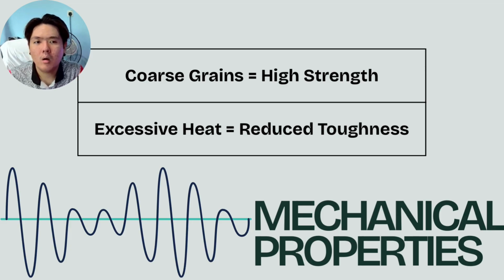So why and how did we determine this problem? I would say it's a problem in welding. Maybe you're using too high a current, maybe you're too slow on your travel speed, or maybe you're doing many passes without it cooling properly. Uneven distribution of heat can cause excessive heat input, resulting in a weak HAZ, the heat affected zone, reduced impact resistance, and also a higher risk of cracking.